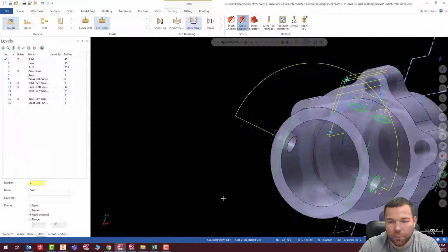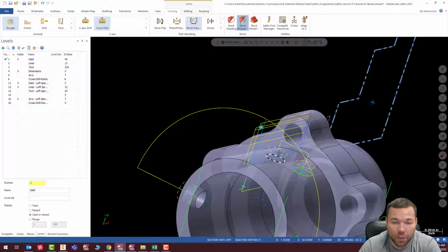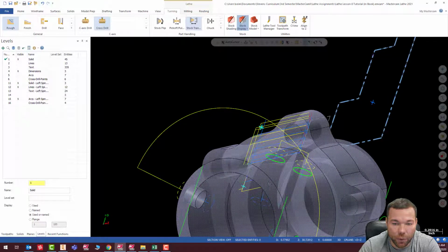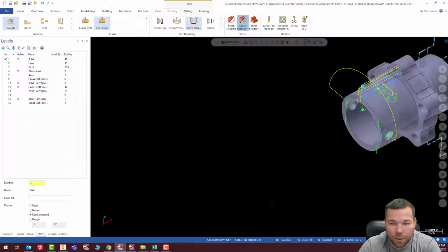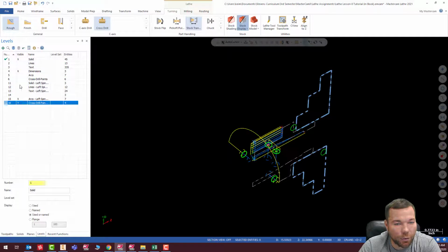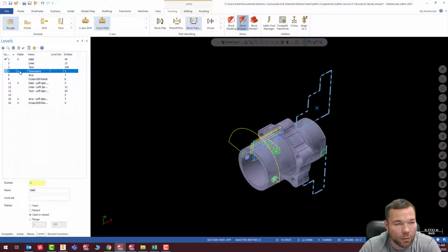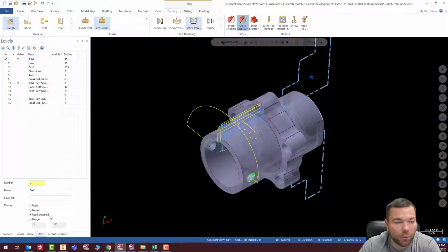So that works. Now, if I was making a bunch of these parts, I may do these as separate. That way I'm not drilling this one forever, and I don't need to go that deep for that one. So I might drill this one separate from this one. Just make it a separate operation. Okay, so I believe that is all we need. Turn everything off there. And let's go ahead and wash this thing complete.